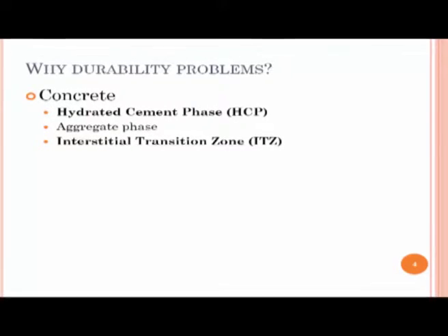We discussed some of this in terms of the impact on how cracking propagates within concrete. If you remember our discussion in the compression test, we saw that first the cracks are formed in the interfacial zone, then these cracks propagate through the matrix and finally form a large network. Okay. So heterogeneity of concrete is one of the primary reasons why concrete is weak in tension and is also poor when it comes to durability in certain environments.